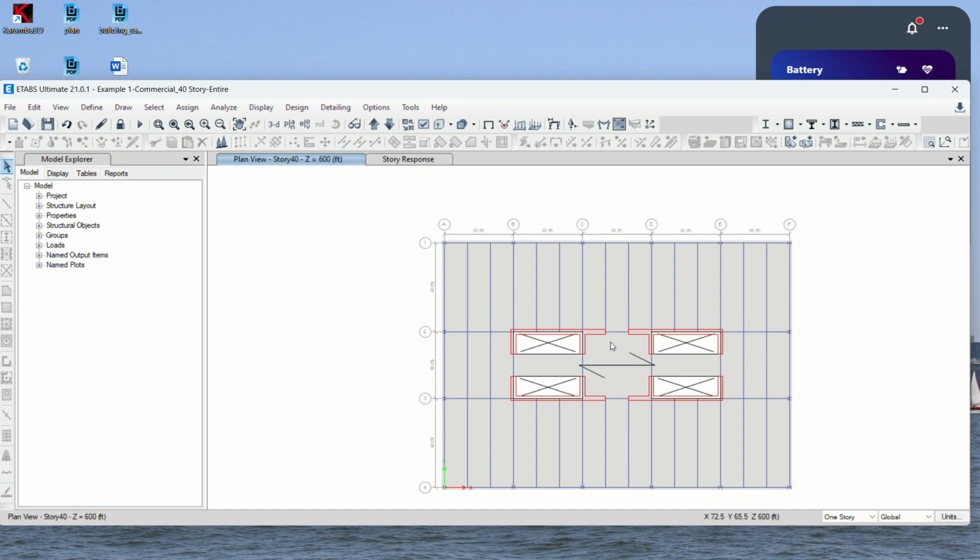So you know which one is the strong axis and which is the weak axis by looking at the core layout. That explains that wind blowing in Y is only a little bit more, 150 divided by 110, which is what ratio, 40% more. Yes, 36% more, but the deflection we end up with is mostly 40 inches divided by 7 inches, right? Almost 6 times bigger.